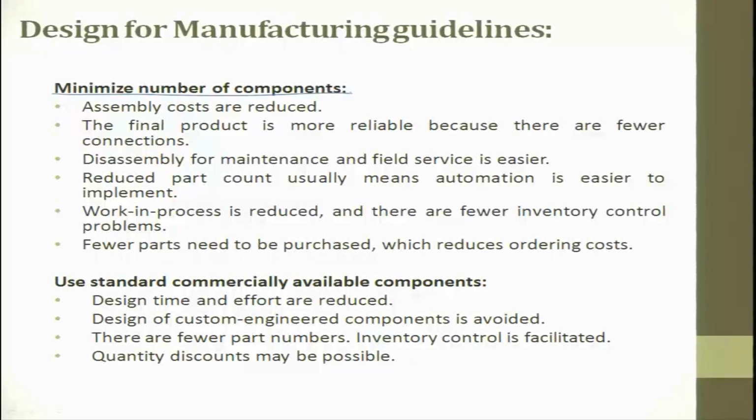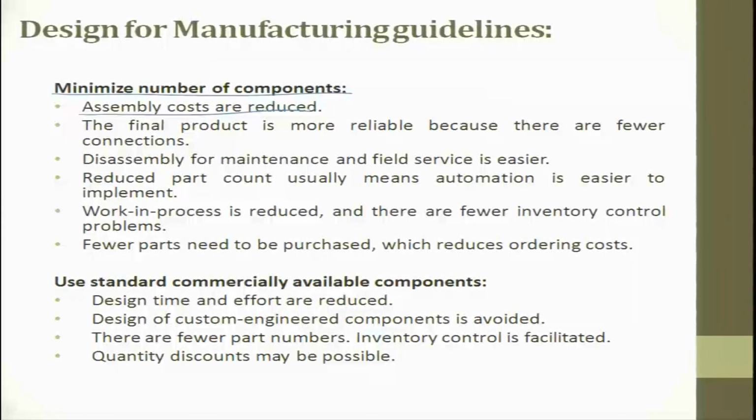In order to avoid this wear and tear and a lot of defects in the assembly line, what people suggested is to reduce as many assembly operations as possible. Then it boiled down to reducing the number of parts. So assembly costs can be greatly reduced. Earlier I told an example: people make furniture in which they don't do assembly. They just